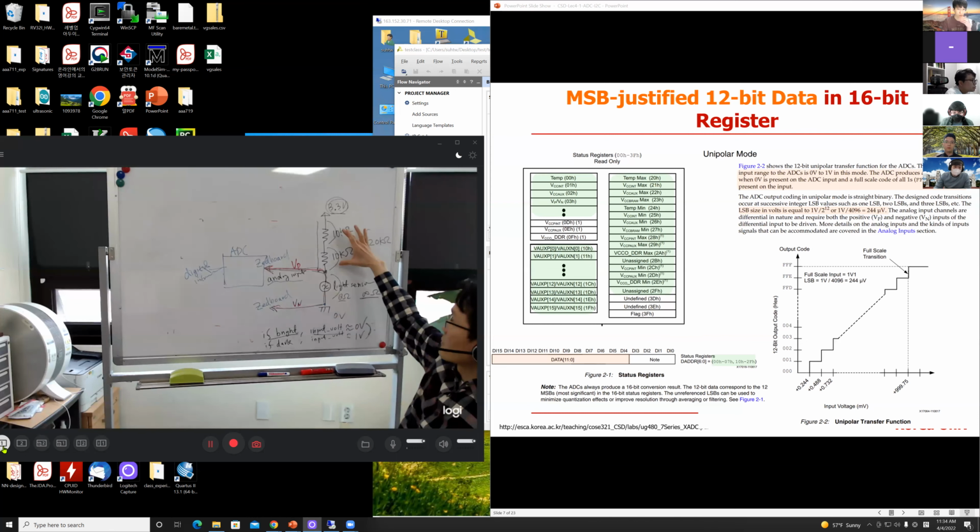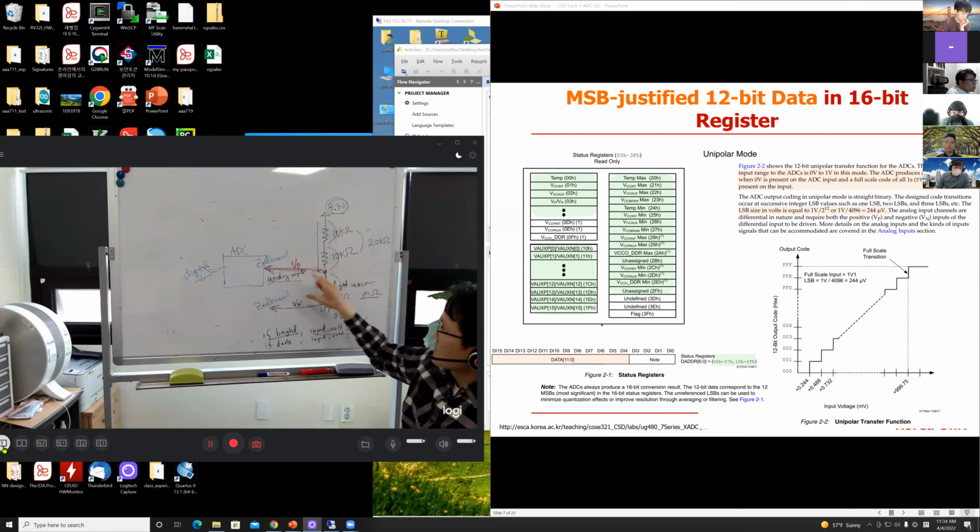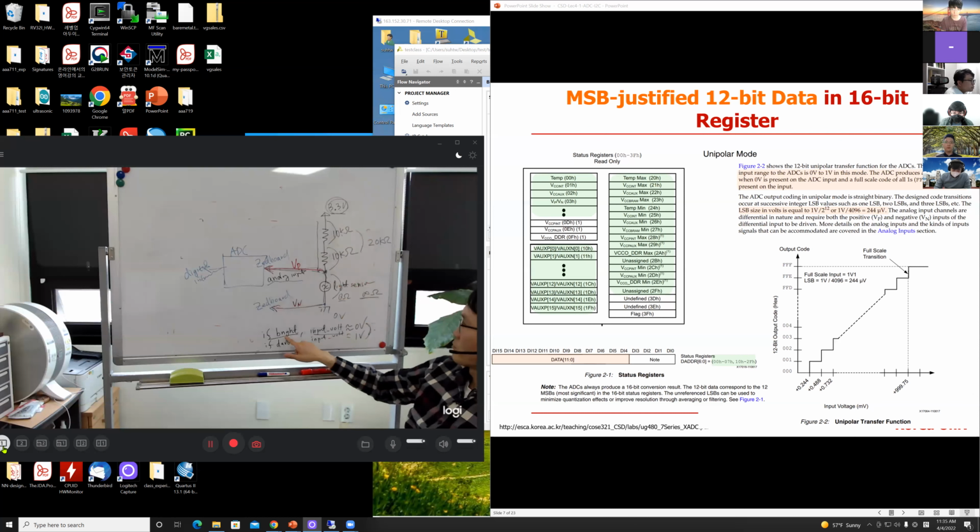I changed these register values to make sure the voltage going into the ADC can be up to 1 volt, because the ADC specification says you have to make sure you are supplying 1 volt or less. So if bright, close to 0, dark, then the register goes up because the voltage is distributed, and it is supplying close to 1 volt. I did all the dirty work, right?